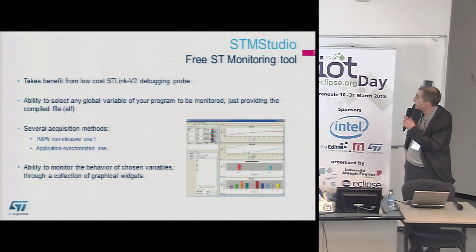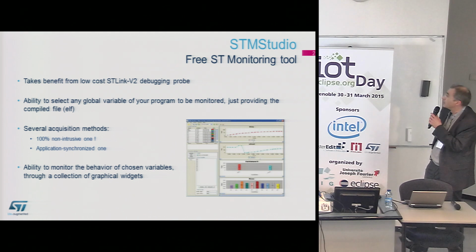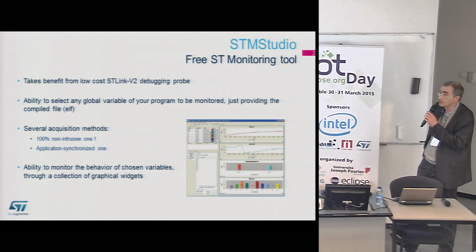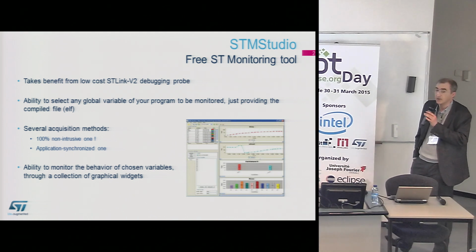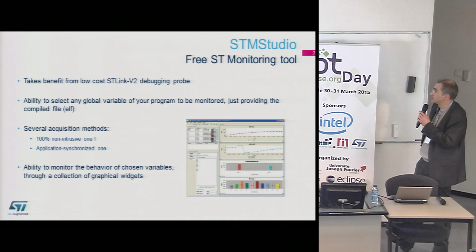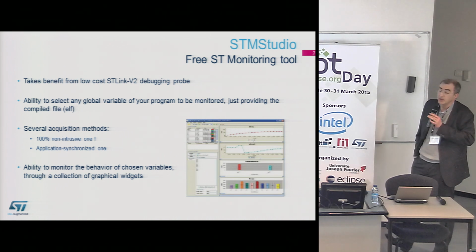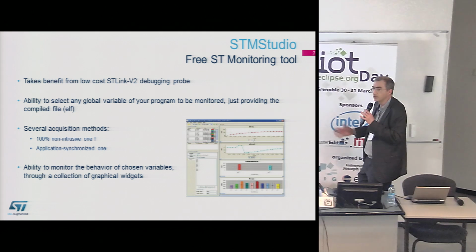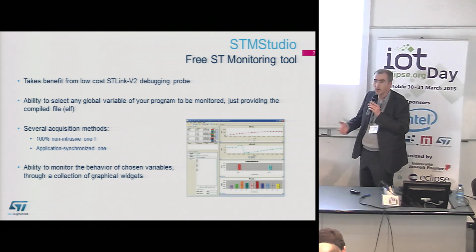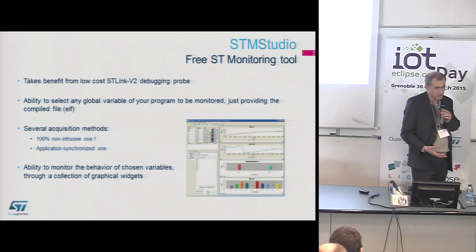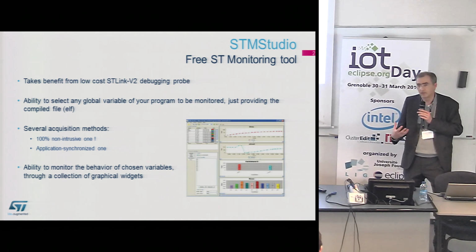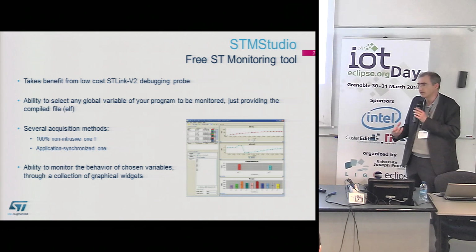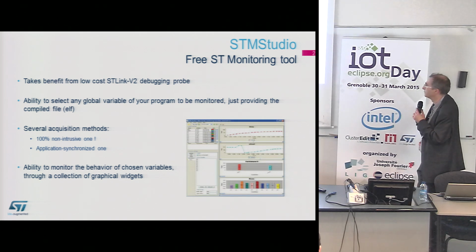So I already talked about the STM Studio, but the idea with STM Studio is that you have a non-intrusive way to monitor your application. It's quite interesting. If you want to be a little bit more intrusive, you can, but it's not the idea. We have two modes of operation in STM Studio: one completely non-intrusive, one more intrusive, to make sure that we snapshot the variables where you want to, when you want to snapshot the variable.